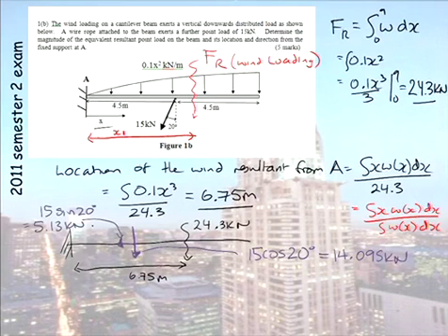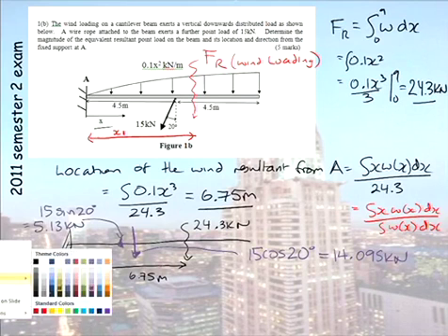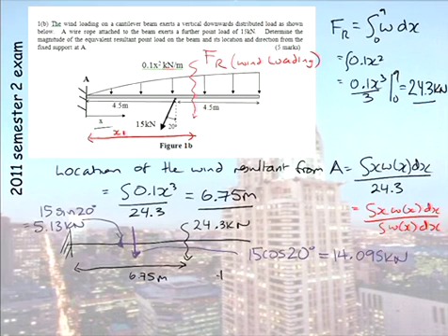So now we still keep the vertical component away from the horizontal component, and we say to ourselves, well, our total vertical force is equal to our 24.3 plus our 14 is equal to 38 kilonewtons. And where is it acting?